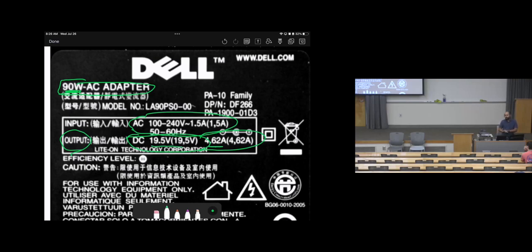Okay? That's how we can realize that this charger can work with either my cell phone or my laptop, with any electronic device, by looking at the outputs. If the output is, for example, 20 volts, and your cell phone is 5 volts, this will harm your device. So don't use it. That's a very important way, which is by looking at the adapter wattage and the outputs.